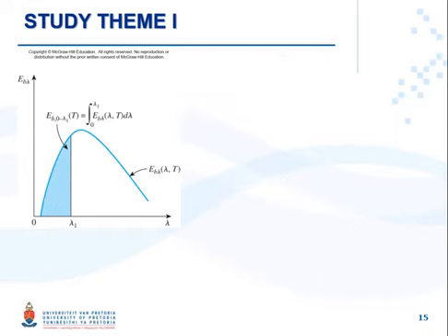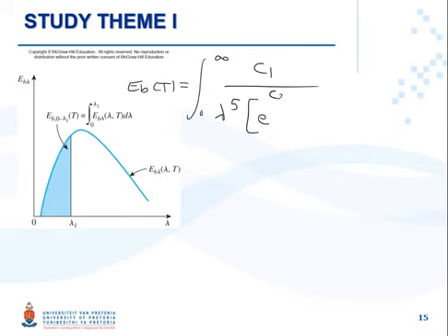Okay, so E_b(T) is equal to the integral from 0 to infinity. I just put Planck's law here: C1 over lambda^5 times e to the power of C2 over lambda T minus 1, d lambda. Okay, so to make it easier, we do a bit of math manipulation.